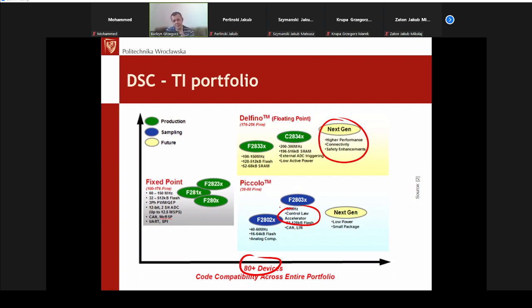Sometimes we've got programmable logic inside the microcontroller, which means that we can change the connections inside and use the block as glue logic for connecting external signals to a microcontroller with functionality tuned to our needs. In case of the CLA, the idea is that we have a block that works with input and output, so it just processes the data. So let's say a micro DSP, because it's only for processing data in a particular way.